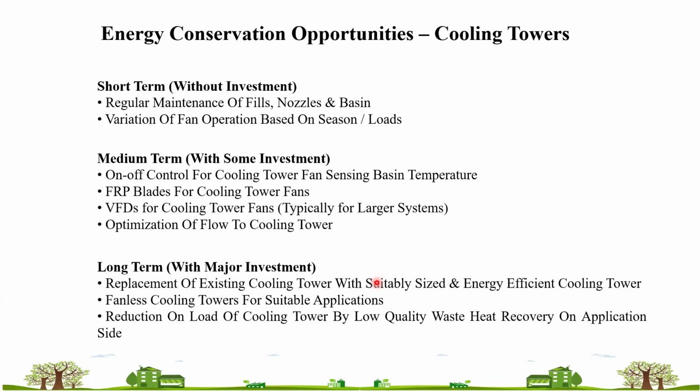What happens if there is an expansion going on in the project, and there is always expansion? You add more utilities to the cooling tower, and that cooling tower is not sufficient for all the utilities, so all your utilities suffer. You need to think thoroughly: this is 400 TR and I am adding 600 TR load to the system, so it will not suffice for your entire system. So you have to be very cautious while replacing this particular system.